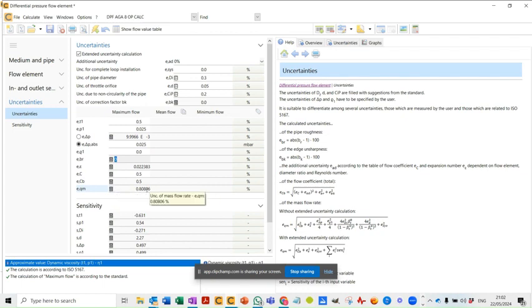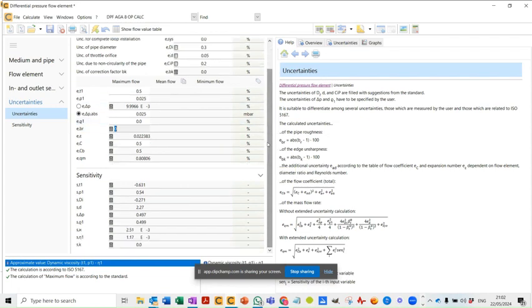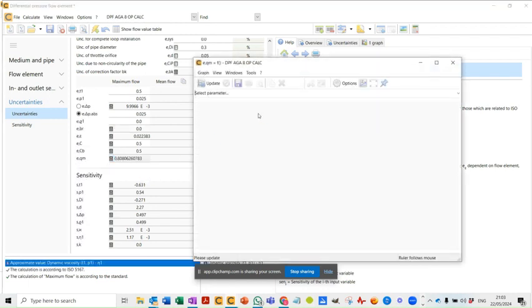error statement for our maximum flow for a single pressure transmitter with an error of full scale. So I'm not going to calculate the error of reading at this stage. So to simulate one of your other high performance transmitters, you can also see the sensitivity coefficients here. I'm going to quickly calculate out the mass flow error over a 10-to-1 turn down. So volume flow rate 2,000 to 20,000, quickly see what our error is without any additional pressure or temperature errors built in.